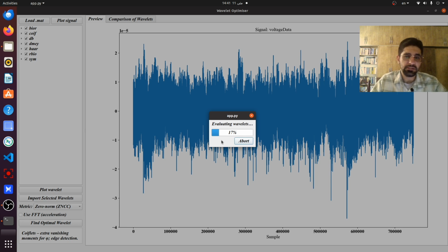But there are various approaches to calculate the similarity of your signal and the mother wavelet. The first one is to utilize discrete time warping to enlarge the small wavelet window and make it as large as the 1 million sample signal, and then calculate the cross correlation of these two signals with identical length once, which is not a good approach because the wavelet is gonna be convolved on short windows of the signal.